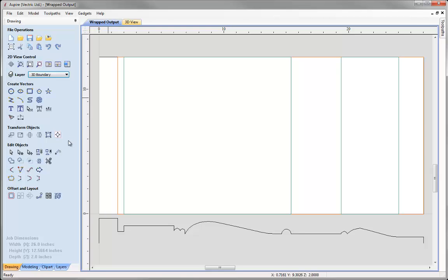Now just before we go over to the Toolpath tab, one thing that can be beneficial when doing rotary machining is to come slightly past the edge of your part in order to make sure that you don't leave any kind of a seam at the top or bottom, basically where the part wraps around and joins up. To help us do that, I'm just going to slightly increase the height of the 2D pocket vectors.